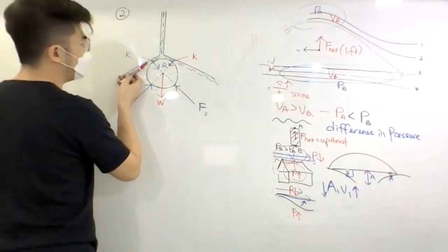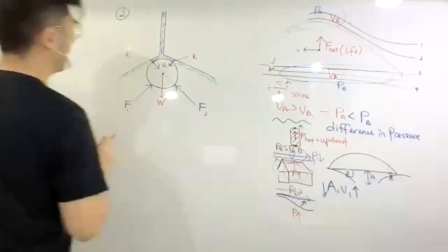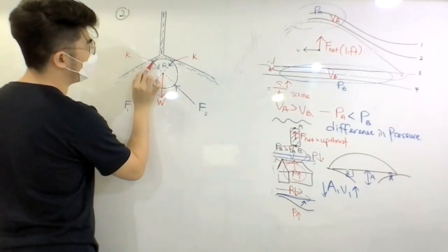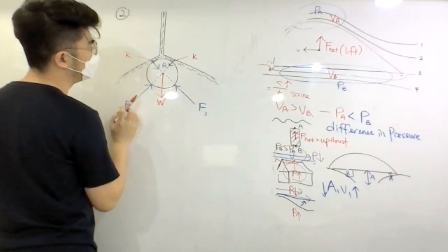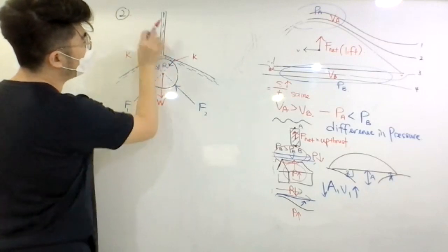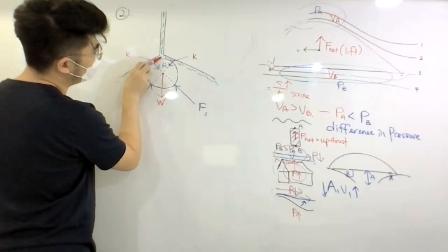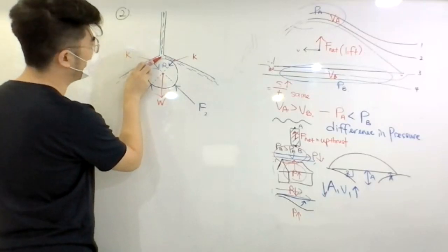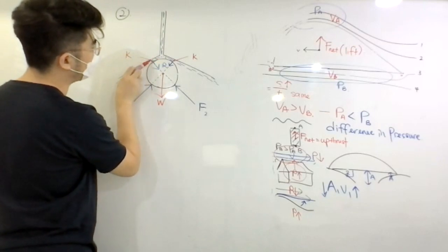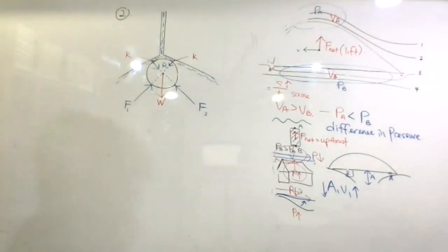Okay, so that is for question 2. The speed is fastest in between the funnel and the ping pong ball, not at the middle, because when the water goes down it hits the ball and there is a stagnation point there. So the water should be faster, with higher velocity, in between.